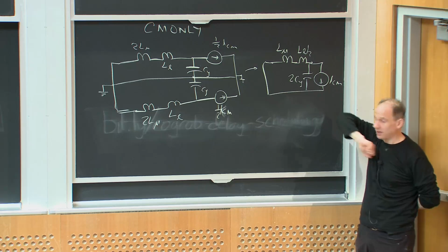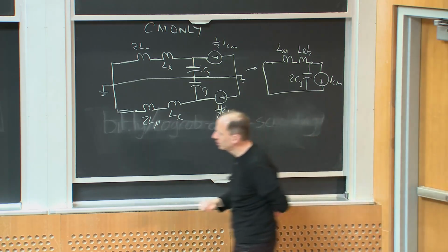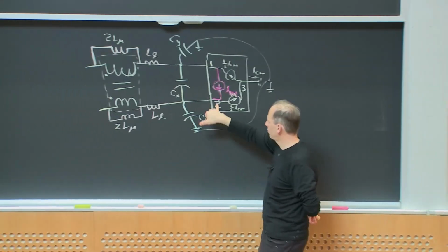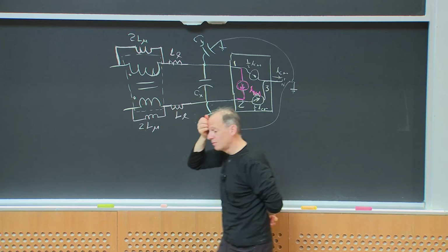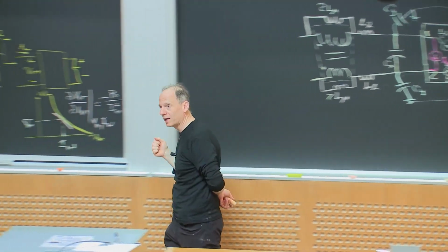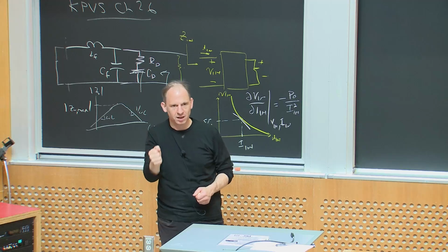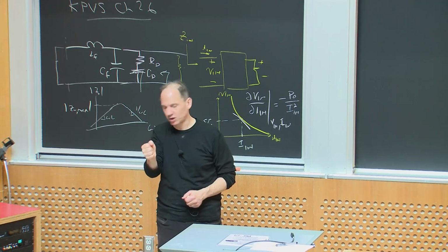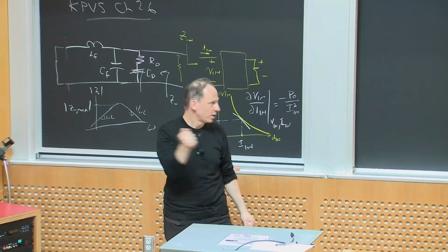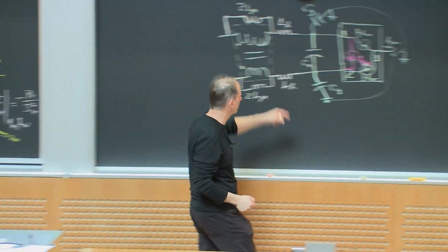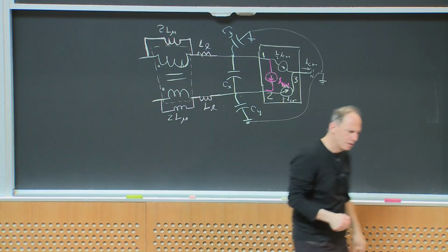And that's handy because this C sub Y, if I come back to my real system, it can be connected between the negative terminal and the positive terminal to ground. It turns out I'm not allowed to use a very big Y capacitor. I'm not allowed to connect a big capacitor between, say, hot, my AC voltage coming in, and ground. Why? Because, first of all, we're not supposed to carry currents in ground, right? This is actually allowing current to flow in the ground wire, right?